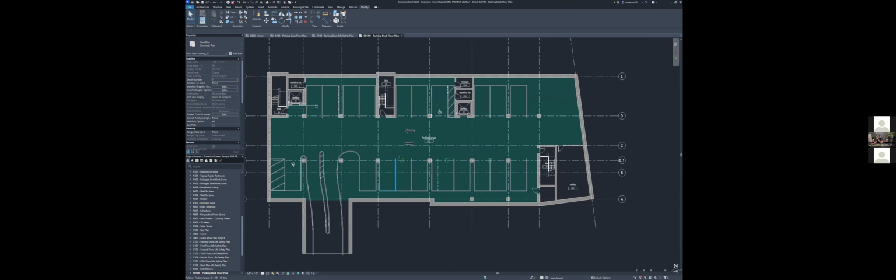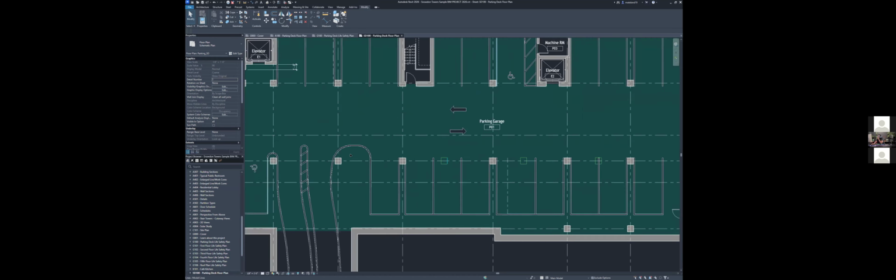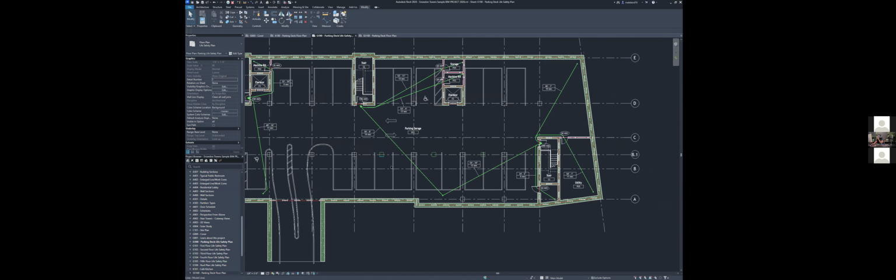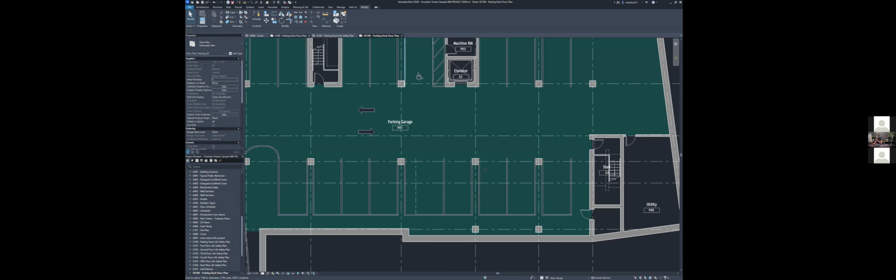So depending on the use case, you might want to show something across all these different drawings, or you may want to show only one thing in one drawing. You use detail lines to show one specific sketch in one specific drawing, or if you want it to be reproduced across all the different drawings, you can use a model line. And as mentioned before, you can convert model lines to detail lines and vice versa by doing it up here again. In the view that we're in, it will remain as a detail line, but we can see that it's not released from the other working files. So that's it for the demo.